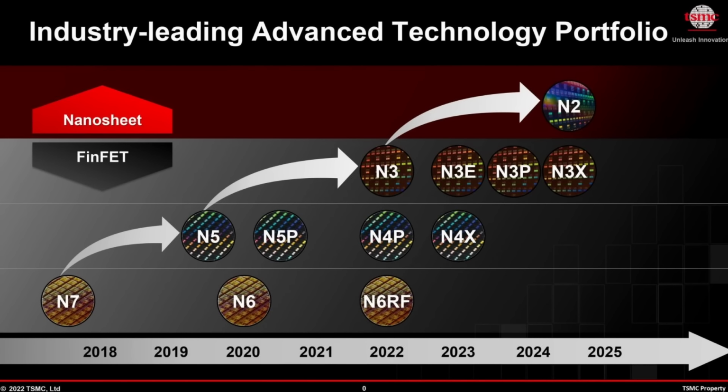The small NAND cell uses the same amount of transistors as the normal one, but each transistor is smaller. The gates are only about half as wide as on the normal sized NAND cell, which reduces the output current. The large NAND cell, although performing the same function as both the normal and the small cell, uses more transistors. Ken Shirriff notes that it's essentially two standard NAND gates in parallel. This allows the large cell to provide double the current. Even back in 1985, the same logic gates were implemented in the form of different standard cells, each with their own unique electrical and density characteristics.